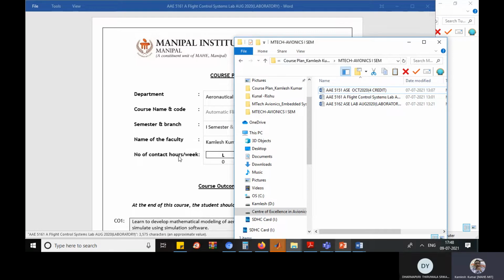Engine weight is very high compared to the motor, and battery weight is very high compared to fuel. If you have that much fuel in comparison to the battery, endurance will be in terms of hours, 2 hours, 3 hours. But the same weight will give you 30 to 40 minutes maximum with an electric motor.